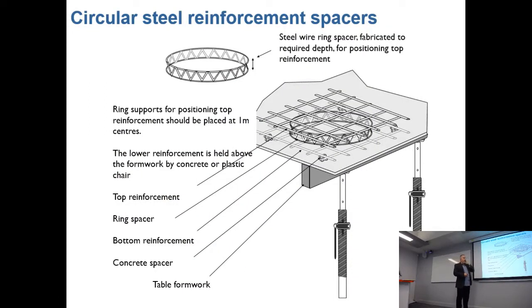But what you do when you have your timber, just before your concrete arrives, is spray or paint on a mould oil. There's companies like Sika who provide this.